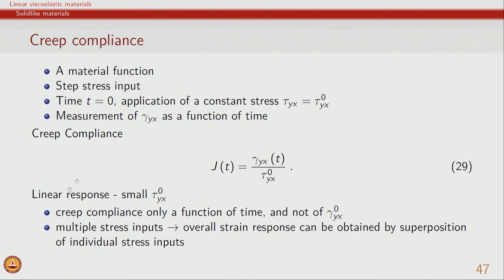With this we have now overviewed stress relaxation, oscillatory shear, creep and zero shear viscosity, all these material functions which are very useful in characterizing the linear viscoelastic response. Just the way we define compliance to describe the creep response, the oscillatory response could also be described in terms of compliance. So in general there are a variety of these material functions which are reported depending on the context of the material and the study.